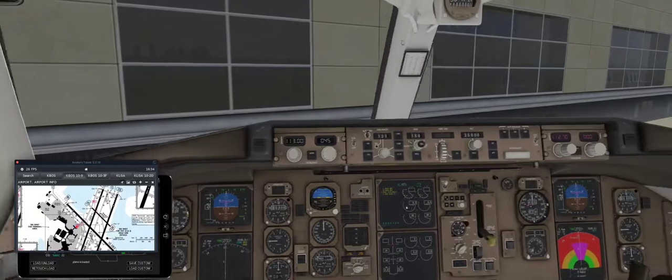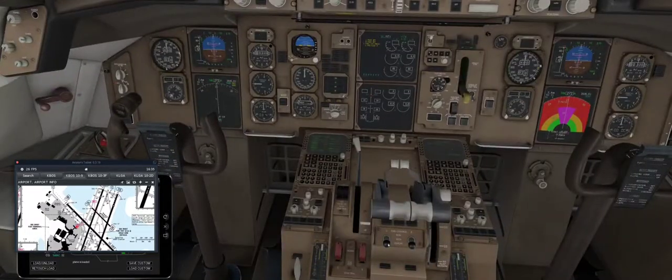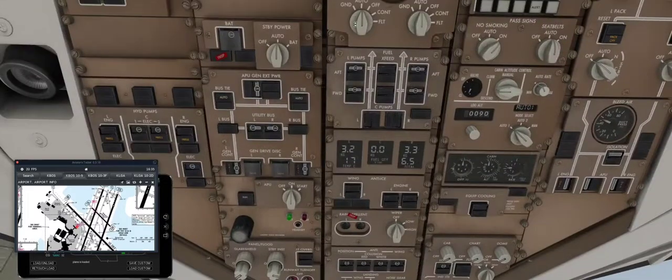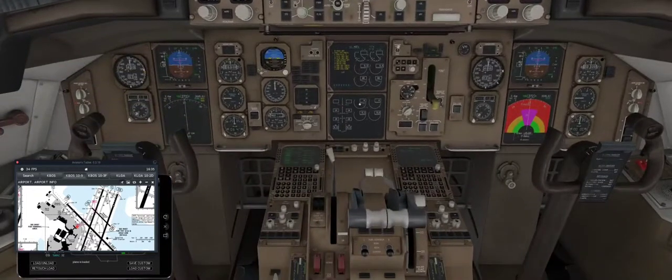And that's exactly what we're going to do. We have to view N2 there. And we're going to do the pilot's side first. Go to ground. Watch N2. I start it when it gets to about 23. If you start it too soon, that's an improper start. You'll overheat the engine while you're starting it, which will likely cause you problems down the road.